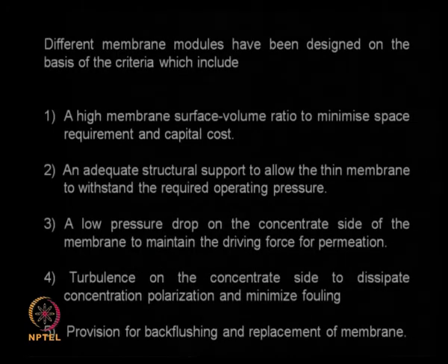Okay. So different membrane modules have been designed based on the criteria of your selection. Generally our goal is to have a very high surface area to volume. Why are we doing that? We want to minimize the space requirement. If we are minimizing the space requirement, we are minimizing the capital cost.